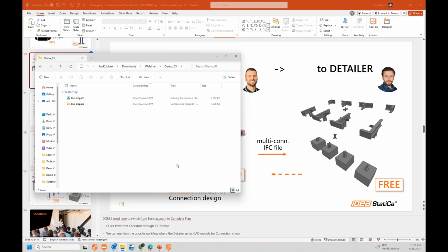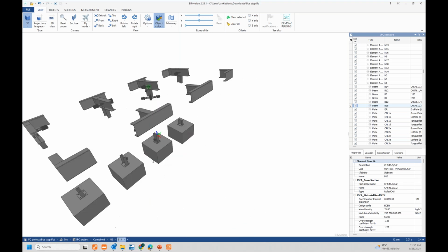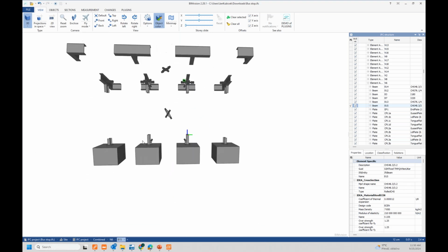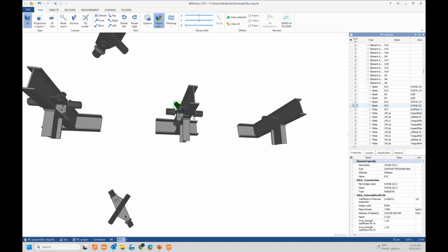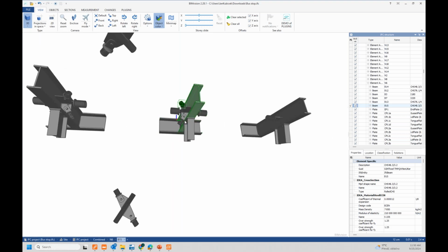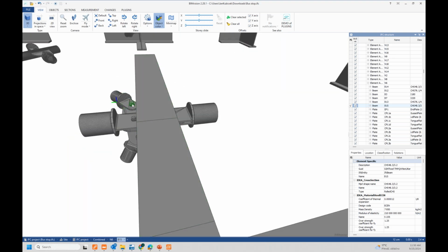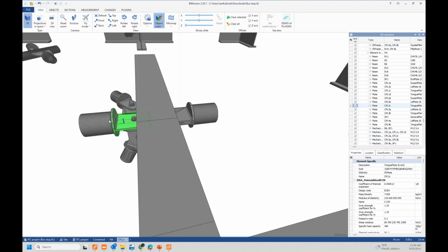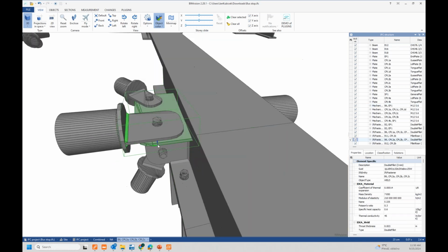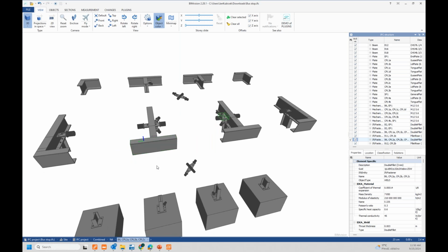Of course, I can open it in some free tool, which is available online, or a desktop version, and I can quite clearly see what I should model or draw in a CAD file, AutoCAD or other tools, in a very detailed way. The IFC model contains information about the bolts, so I can see the sizes and materials, the same for plates, the same also for welds. So this is very useful, and I know where to start with modeling.